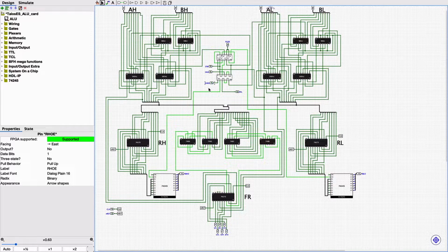And one way to buffer them is to invert them through a Schmitt trigger inverter. And then you also have a boosted signal in which you got rid of some of the interference because of the Schmitt trigger. And in this case here, it's the same thing. I'm using this inverter here as essentially a buffer that boosts this signal before it finds its way to the transceiver on board, on the same card as the rest of the circuit here.